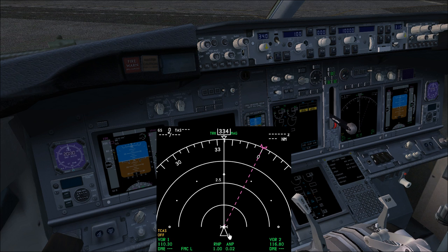The IRS positions are asterisk-like, and those triangles are the GPS position. While flying, those move around the airplane because the positions of these sensors are different from one another, and you can see that one is slightly different in position with respect to another. In this case, they are all together because we are not moving, and we have aligned the IRS here.